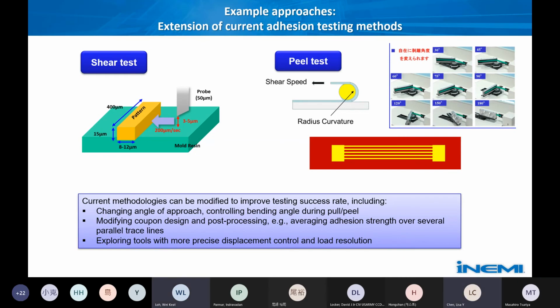I think this is a very good one because as the traces and the copper flatness or roughness requirements get tighter, obviously that will trade off adhesion strength, right? This kind of method would be good for material development and test development, to ensure they have a very good test method to evaluate whatever adhesion promoters they're trying to use here. Yeah, definitely. Thank you, Vicky.